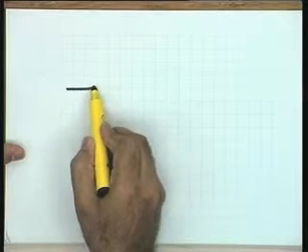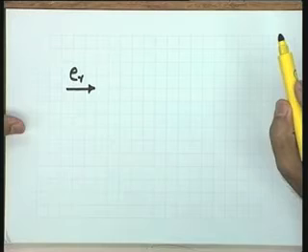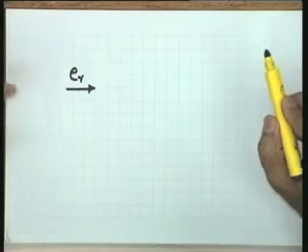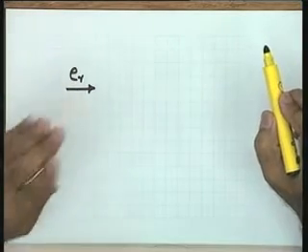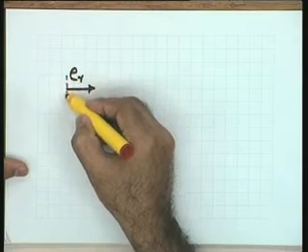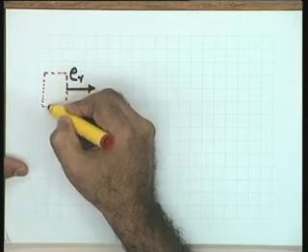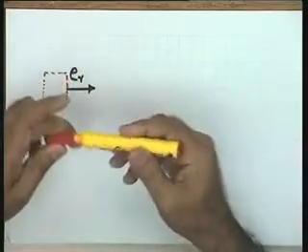Okay? I may refer to this diagram again. I need your help now to set up a block diagram. What I do is I take this as the reference signal ER. This is the reference signal which is proportional to, or which is a function of, the commanded signal omega r. If you do not mind, though the physical diagram does not have this component, let me have this component and call it the reference input elements.